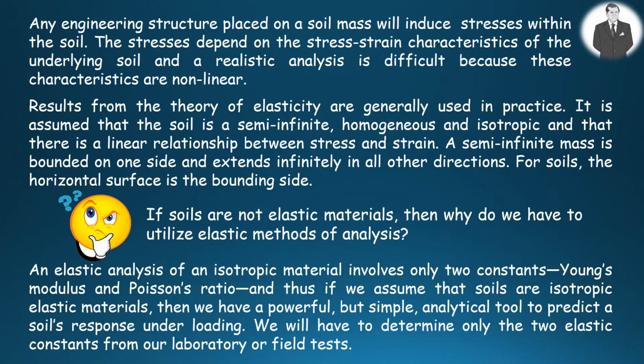Therefore, if we presume that soils are isotropic elastic materials, then we have a powerful but simple analytical way to predict soil's reaction under loading. We ought to determine only the two elastic constants from our laboratory or field tests.